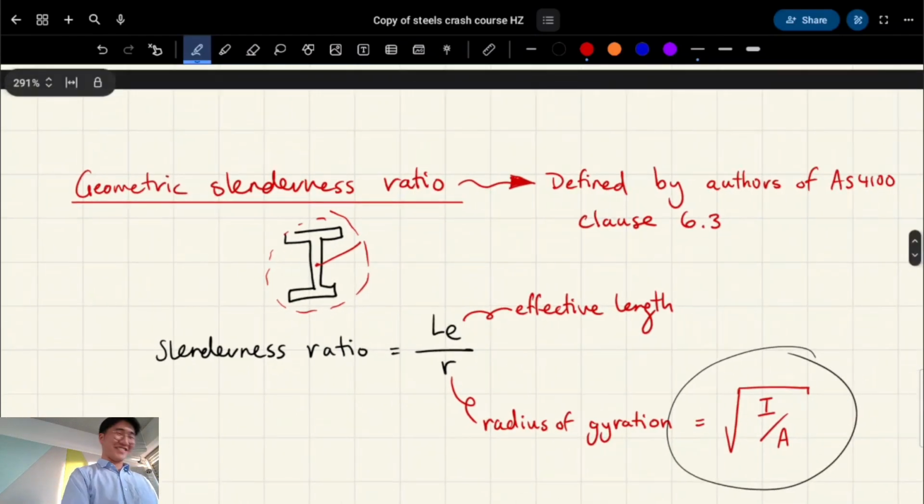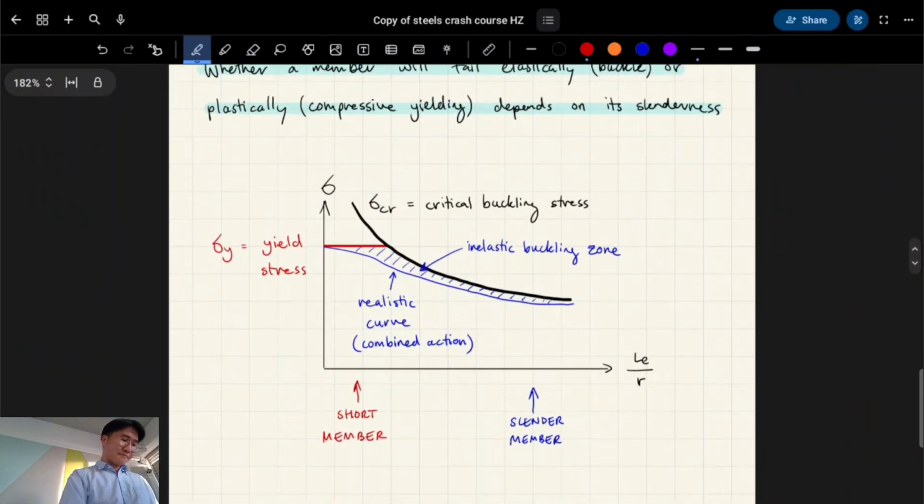The last thing I want to mention is that buckling is an elastic mode of failure. So in terms of your material curve, you actually never really cross into the plastic region for it to fail. Because none of the material has actually permanently deformed. If I unload it, it'll return to its original elastic shape. Make sense? So buckling is only in the elastic. Buckling can cause a plastic failure later on, but it will weaken your member significantly.